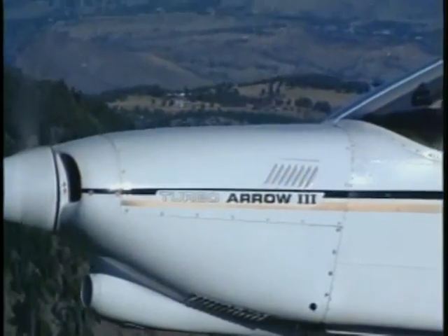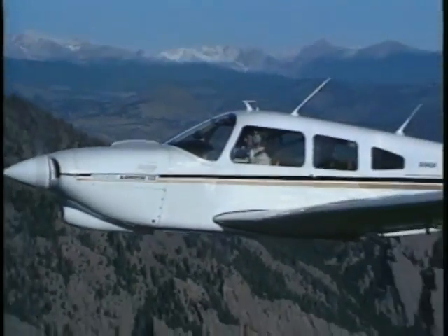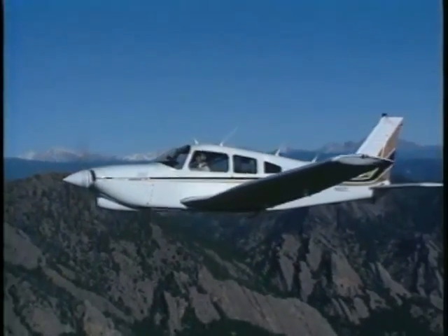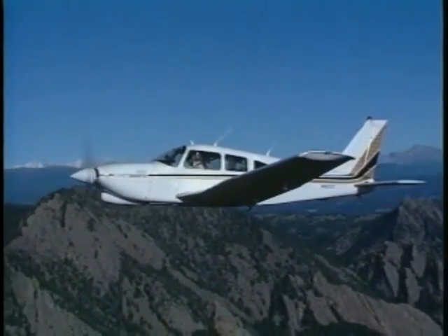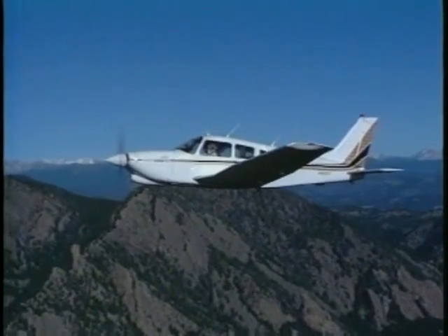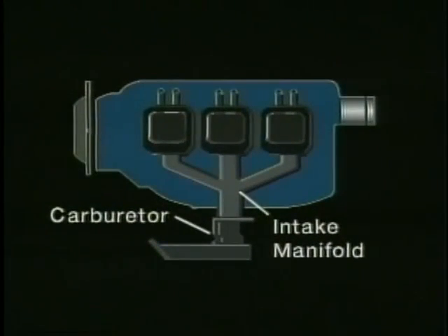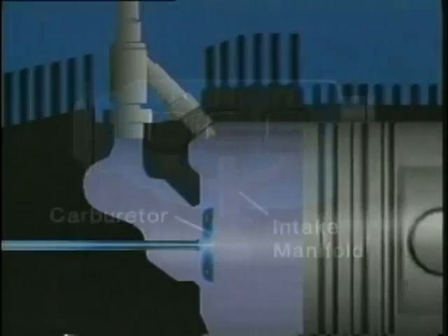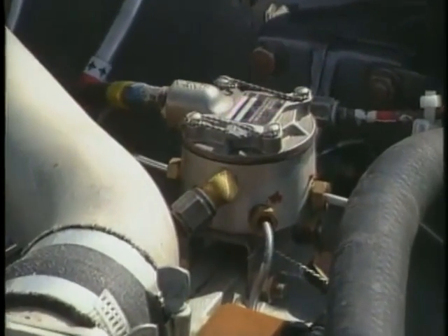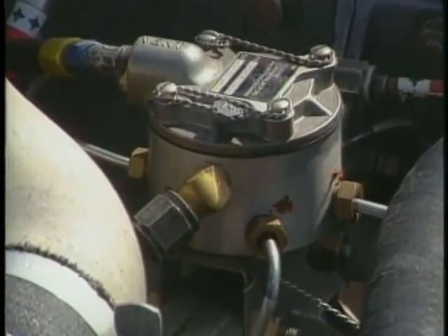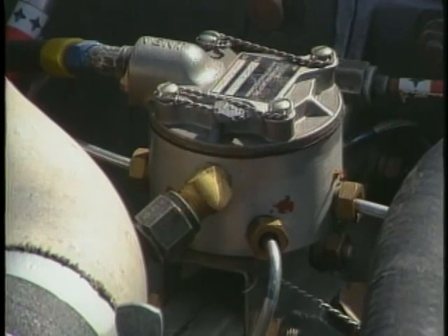In an effort to gain the maximum amount of power from small lightweight aircraft engines, manufacturers have devoted a great deal of engineering research to advanced fuel induction systems. One of the most successful of these is fuel injection. Unlike a carburetor which mixes fuel and air prior to reaching the intake manifold, a fuel injection system injects fuel into the intake port, where it is mixed with air just prior to entering the cylinder. This allows for an even distribution of fuel to the cylinders and a more uniform mixing of the fuel and air.